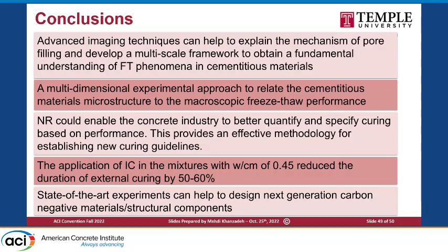We can use these advanced techniques to help us understand and explain the most fundamental observations about the different durability mechanisms associated with mass transport, right? We can combine the modeling with the experiments to predict the service life in freeze-thaw environments for different new materials and for different new admixtures. And also we can understand the impact from internal curing or any other curing, in order to sell this new type of curing to the practitioners.